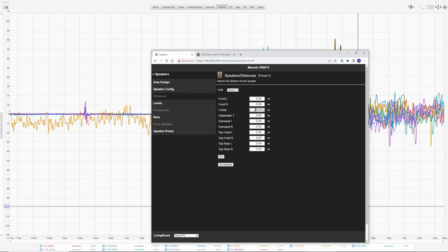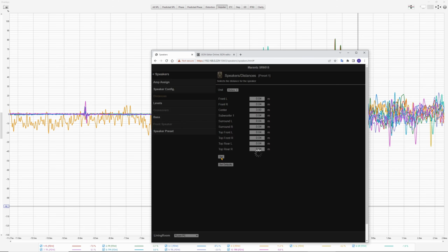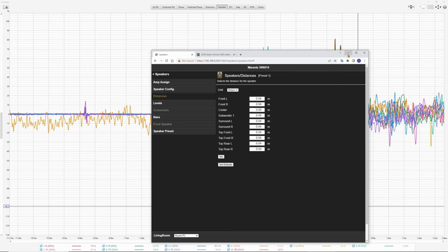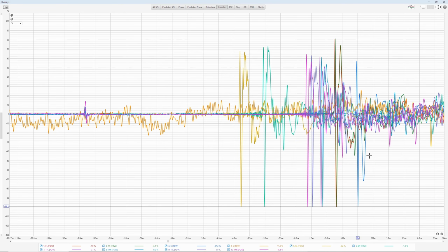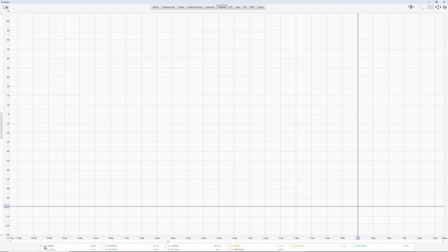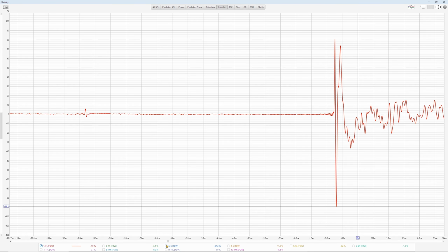So you measured your center speaker distance to the tip of the microphone, and you found it 3.00 instead of 3.01. You could find it 2.95, but for ease of calculations, because we're gonna use this 3 meter quite a bit, so you didn't accurately enter this, doesn't matter, just set the distance. So now center speaker is at 3 meters. From here on, to correctly find out the speaker distances, you just measure their distance to center speaker.